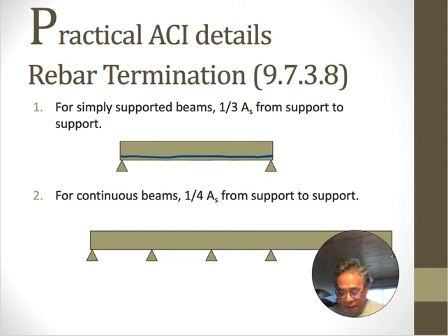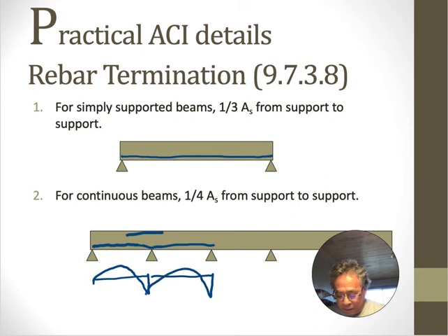And if it's continuous, so there's steel that goes like this, and that moment diagram looks like this. You only need the positive steel where there's positive moment, but it doesn't matter. 1/4 of the steel has to go all the way across the span, no matter what. And this comes from experience. These kinds of continuity details help the beam stay together and perform well.